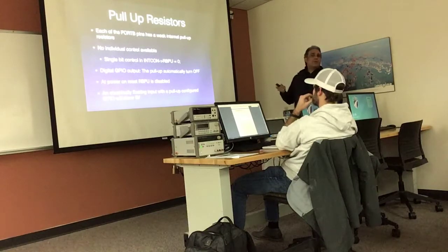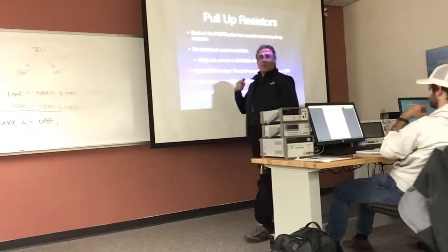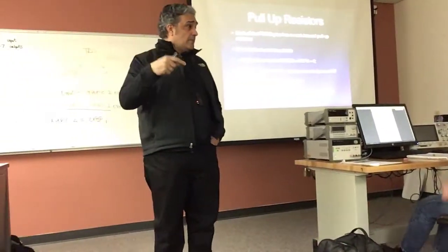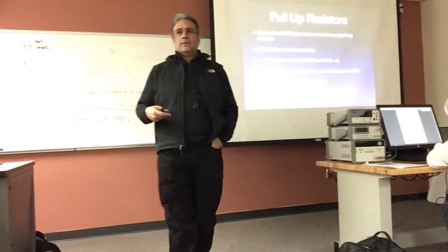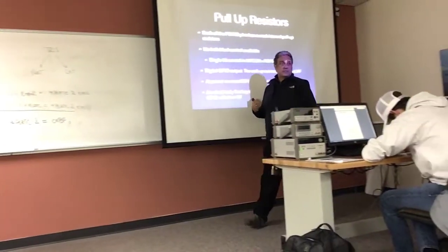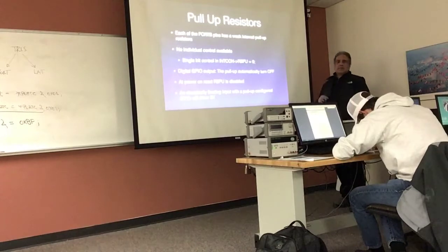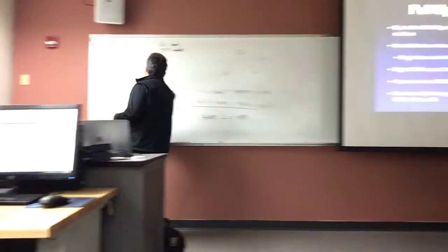Something interesting about port B, and I think this is very, very important for you to remember. Port B is the only port that contains internal pull-up resistors in it. All right, and these internal pull-up resistors are very useful when you're doing input interfacing. And we're going to talk a little bit about input interfacing later. Let's just do it right now so that we can get it out of the way. It's easier this way.